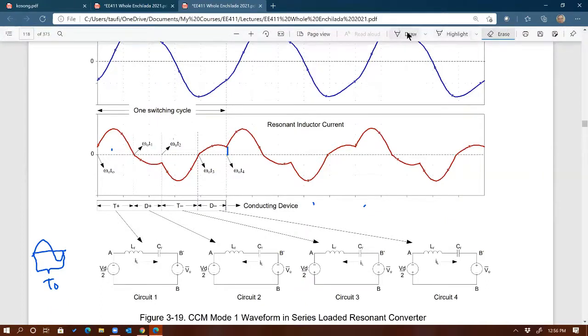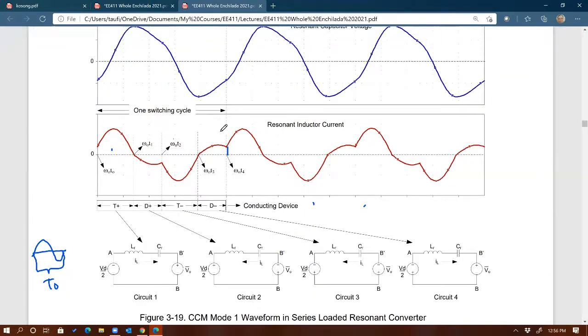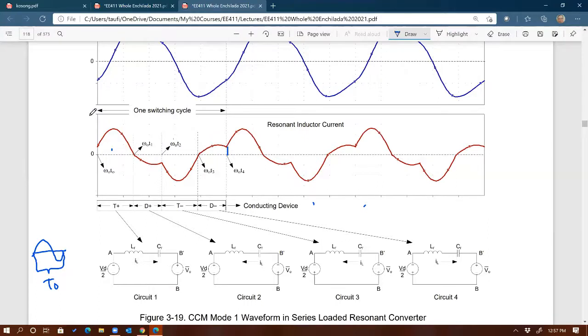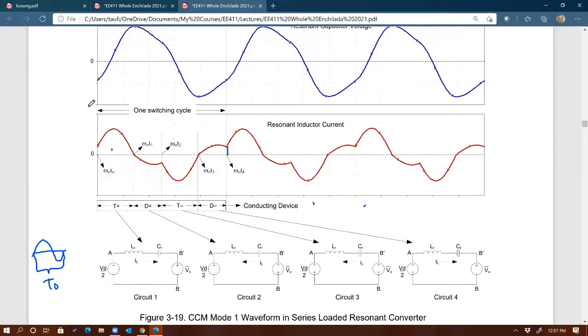The reason why I want to say that is because Schottky, I believe I mentioned that last time, the voltage rating of a Schottky diode is very low. I think the one that you can purchase nowadays is around 250 volt reverse voltage, right? And this is typically used for high voltage. So you need to have a fast diode, but if you use Schottkys, then you have to put probably many Schottkys in series, right? Which is probably not a wise way to do it. So you can buy a higher voltage diode that has a fast recovery time. They call them fast recovery diodes. You can Google it.